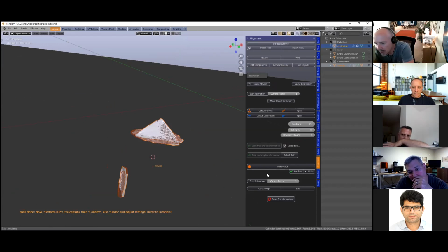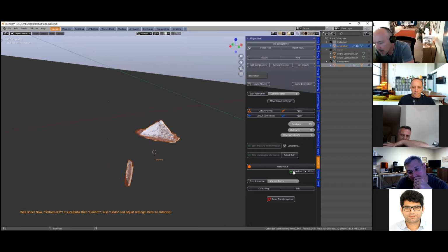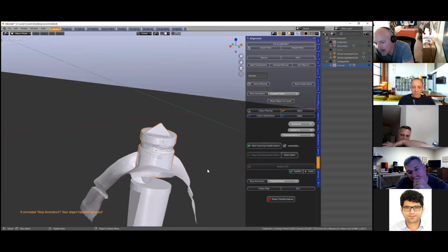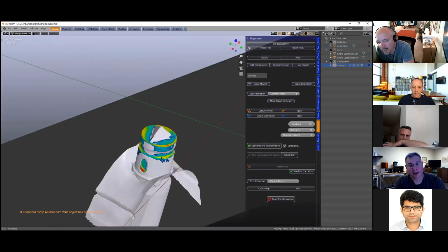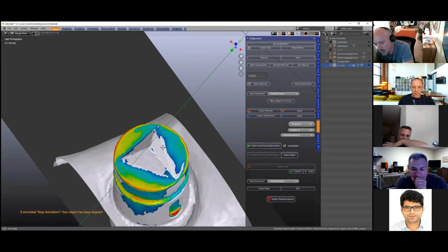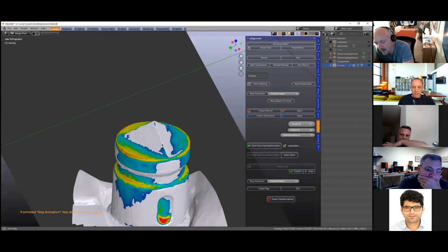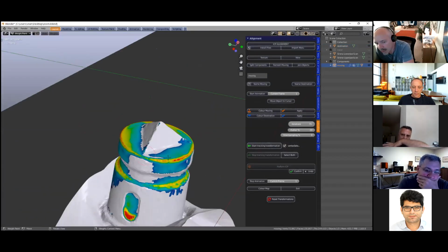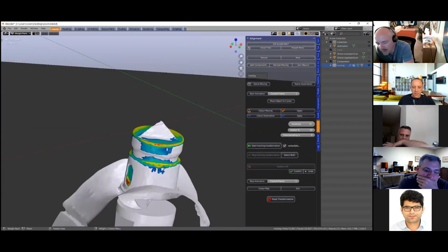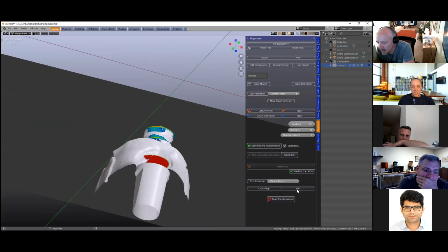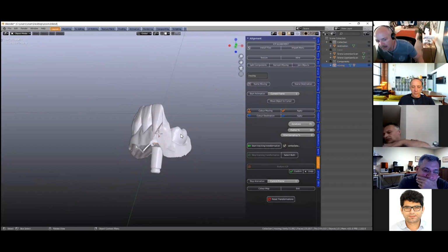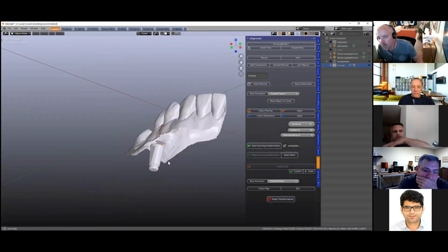And then we're going to click on confirm, and then we can have a color guide. You can have a look. The blue is the contact areas. The red is no contact, or minimal contact. And this seems to be quite good. And then I'm going to click exit. And that sort of completes our ICP, except for one more thing.